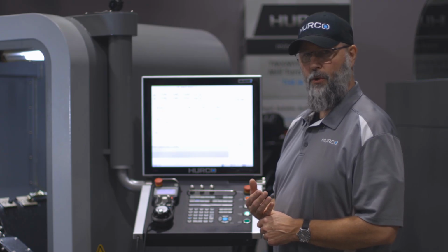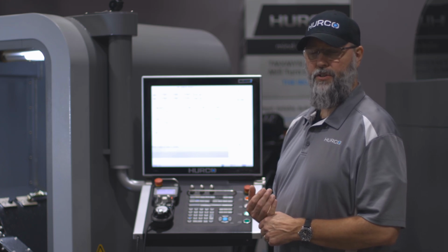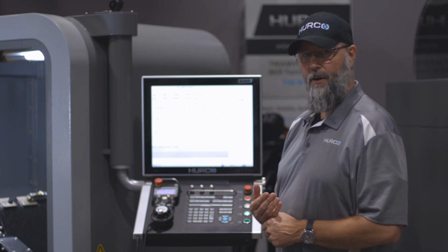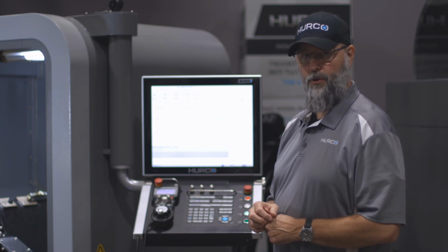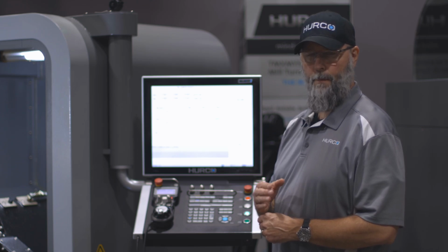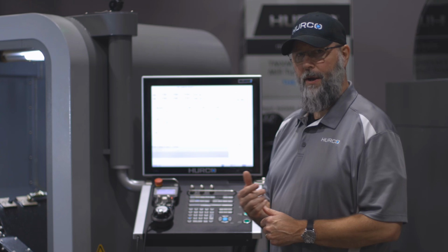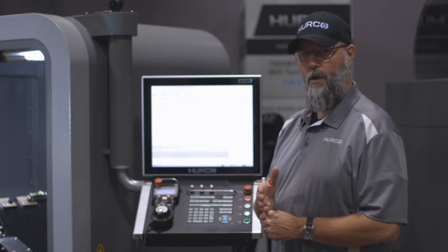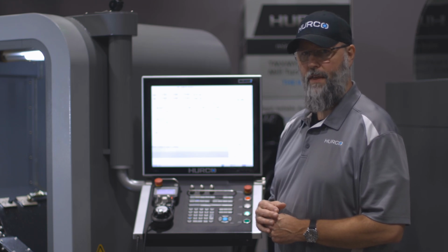Then I'm going to take that tool and I'm going to go down and touch the face of my part. That's going to register my part setup. So from now on, I'll put no value in the Z field for the master tool. And I'm going to use that tool to set my work offset or my Z0 for the part. Then I'm going to touch all my other tools off normally, and we're going to get a value that goes in those tool lengths that is in reference to the tip of this tool. And I'll show you that in a minute.